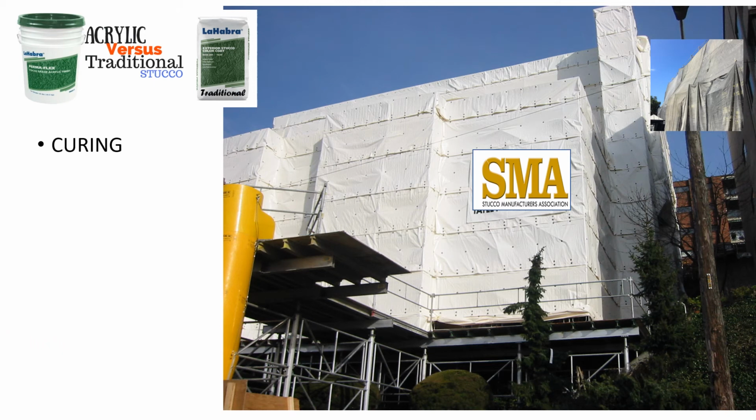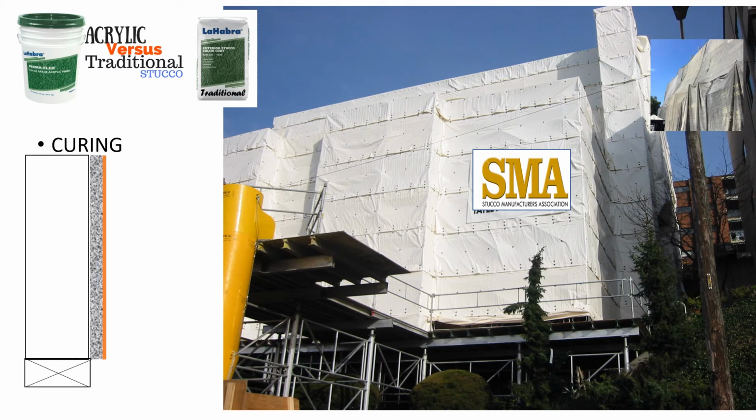There are differences between acrylics and cements, or what could be called traditional finishes. While both products cure, cement is less weather sensitive and it can even cure underwater. Acrylics need air to dry, set, and cure. Both products, when set, are durable and suitable for all climates. It is common to have tenting for projects in cold regions of the country that will receive an acrylic finish coat. It is important to understand how each product sets and cures.